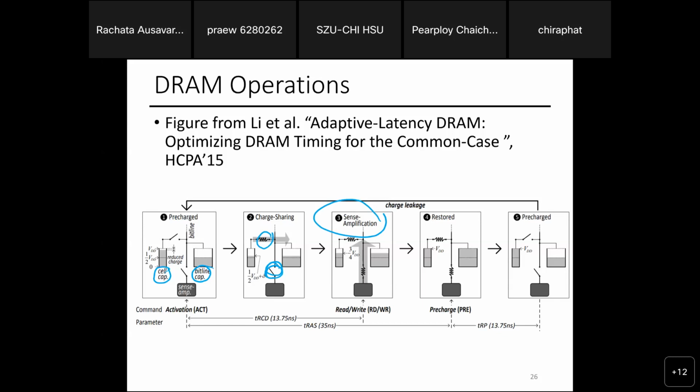The next thing that happens, every single capacitor will start seeing more electrons flowing in. With me so far? Somewhat. So the amplifier makes it more clear for the system. And it also makes sure all the capacitors now, if it's more than 1/2, are filled up. If it's lower than 1/2, it drains everything.